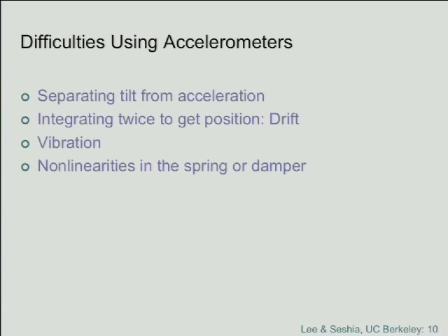So they would apply a low-pass filter so that, for example, they could rule out... If I'm shaking it back and forth, I can get 1G pretty easily, but I can only get 1G at 2 or 3 hertz. So they could rule out anything that's a higher frequency than a fraction of a hertz, on the assumption that you're not really interested in reading your email while rotating the iPhone, right? So this is the issue of separating tilt from acceleration.